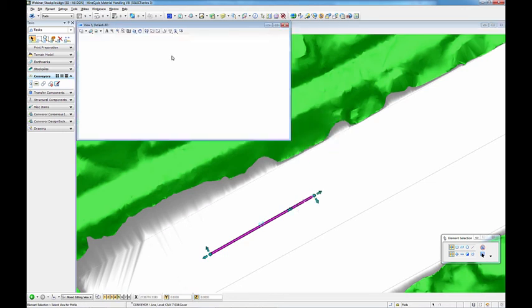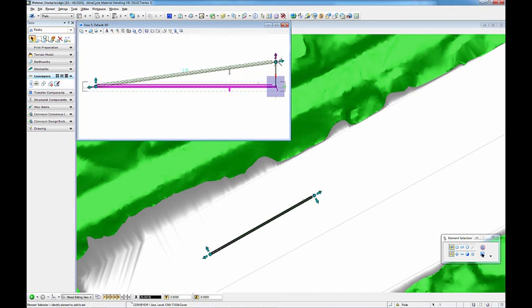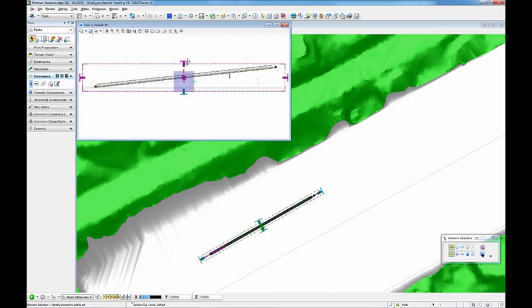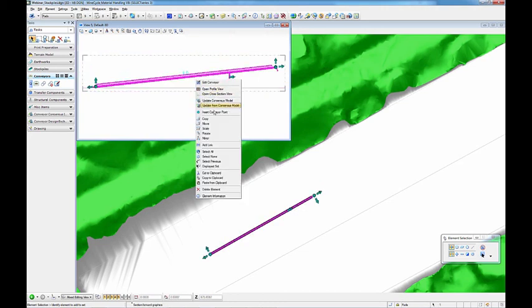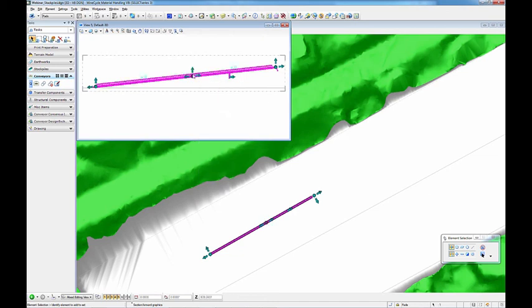Initially, head and tail points can be modified, but if a profile view is displayed, elevation can be adjusted and a new control point can be inserted. This allows control of additional properties of the conveyor, including the incline and decline angles. Optimization of ground travel can be performed to minimize the amount of costly elevated travel. As the conveyors are rule-based, parameters like minimum radius can easily be identified and rectified. Additionally, visual interference checking can be performed.